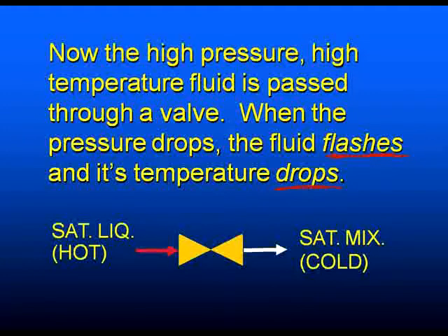So we come in as a hot fluid, come out as a cold fluid, at which point it's a saturated mixture, part liquid and part vapor. And now we can start the cycle all over again and go back into our evaporator.